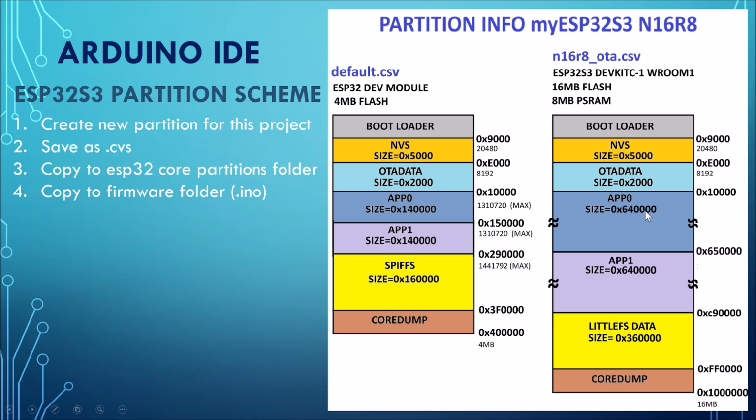So this supports 2 app partitions where we can handle the code for the application, so it handles OTA. These are significantly bigger than the previous app partitions. This isn't to scale, by the way. It has a huge increase in data storage, so this is going to be suitable, looking out into the future as well.